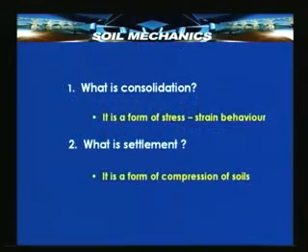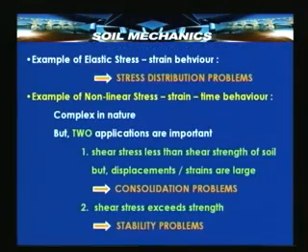Another possibility is the shear stress may exceed the strength and there could be failure of the soil. These problems are broadly classified as stability problem. There are variations in this: stability of an embankment or a slope, for example, stability of a foundation.